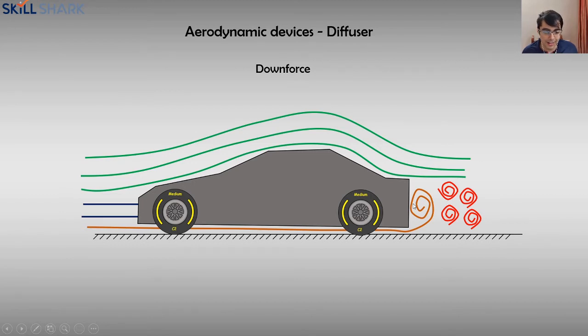Now air underneath here, if you have an edge over here, gets rapidly released. Rapid expansion might be good because air is being sent back out and you have an acceleration of air, but it's also uncontrolled. As a result, you have a lot of turbulence that gets formed here. The downside to turbulence is it's very low pressure. Turbulence has a lot of low pressure pockets, and it's very difficult to tell where those low pressure pockets are and how big they are.